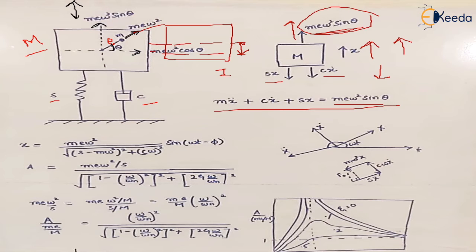Now, if you look at this equation, it is similar to the equation that we have already discussed while doing forced vibrations for a damped system. There the applied force was F naught sin omega t or cos omega t. So what exactly is changing? If the force F naught sine omega t is acting on the system, you can understand that in the equation of amplitude we found initially, only the value of F naught will change.